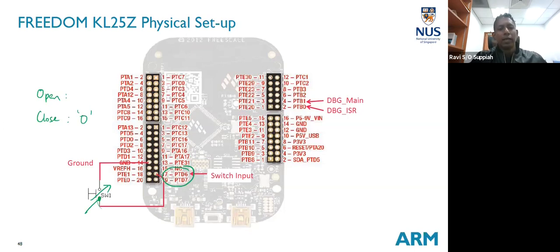But it can be used in our context, because of something that we have also seen before, which we're also going to see here, something internal to the GPIO pin that we can enable. Anybody want to guess what is that? Yes, correct. It's a pull-up resistor. So if you have pull up or pull down internally, then you can use this configuration.